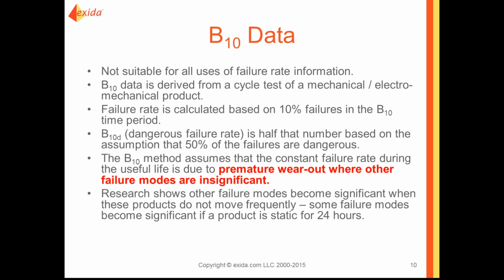where it's being used and cycled and where wear out would be the predominant failure rate, but it's not as useful for an analysis or an application such as a process industry safety system, where a predominant failure rate could be something such as binding. Studies show that even if a device sits dormant for more than 24 hours, the forces required to move it increase dramatically, and therefore the modal distribution between wear out and, say, binding shifts pretty dramatically.